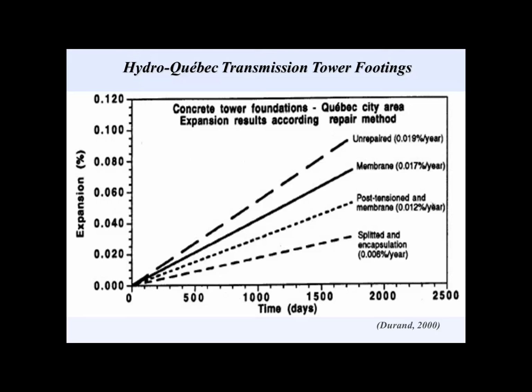Well, certainly it might, but the experience with these dams is by the time you actually pull that wire all the way through the dam itself, there's so much stress that's still built up, it will actually close right behind it. In fact, the early trials had a lot of issues with getting the diamond wire actually stuck during the cutting process itself. So I think because of that effect, there's so much built-up strain and stress in that dam that it eventually, or in fact almost instantaneously, will close behind it.